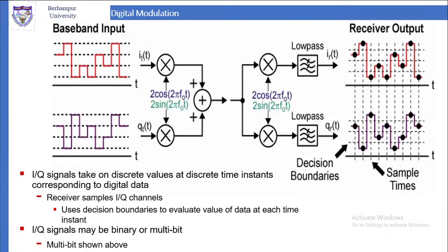That is what is shown here in the baseband. The horizontal dashed lines are the levels. Since the signal has been discretized, it is no more continuous, so it looks like this. The signal is at this level or that level. How will the level be fixed? If the value is between the lowest dashed line and the dashed line above it, and it is below the middle, it will be the lowest value. If it is above the middle, it will be the higher level. So it is the dashed line nearest to the signal value that gives the discrete value of the signal.